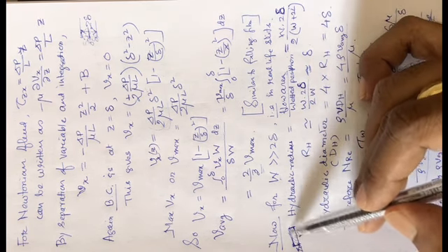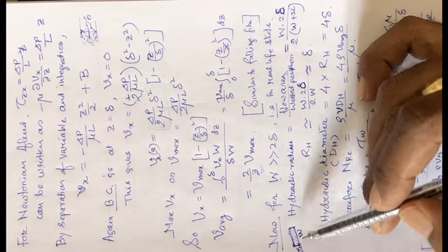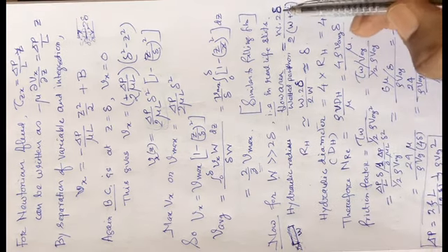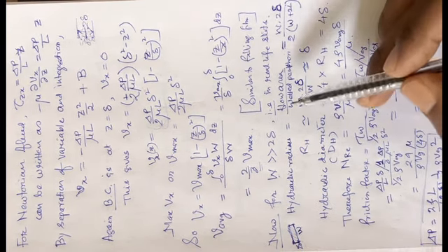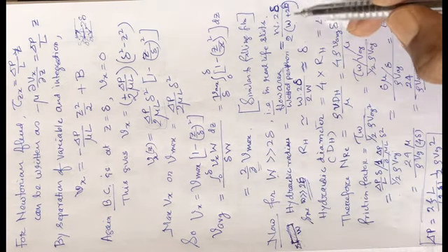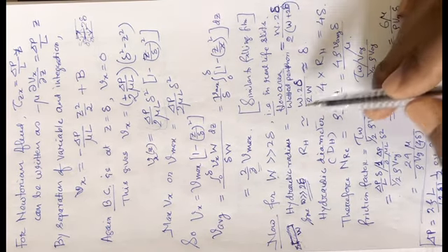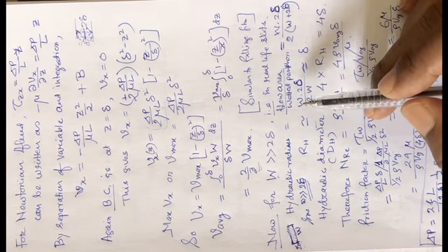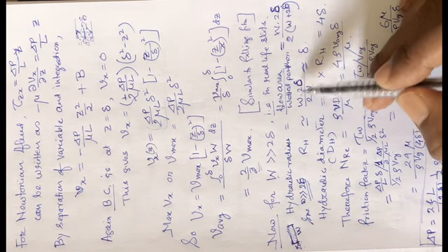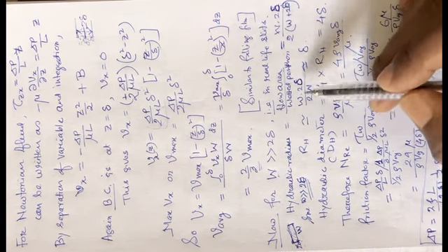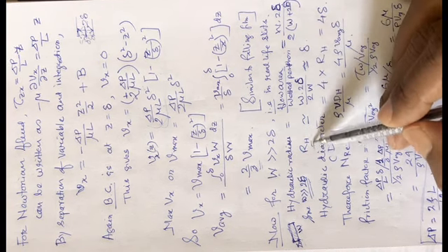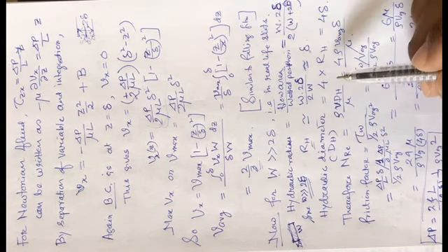Therefore, the flow area is W into twice delta. Okay. Then what is the wetted perimeter? 2 times this, approximately equal to W. So the denominator is 2W and the numerator is W into 2 delta. So it comes out that the hydraulic radius is equal to delta, meaning half thickness.